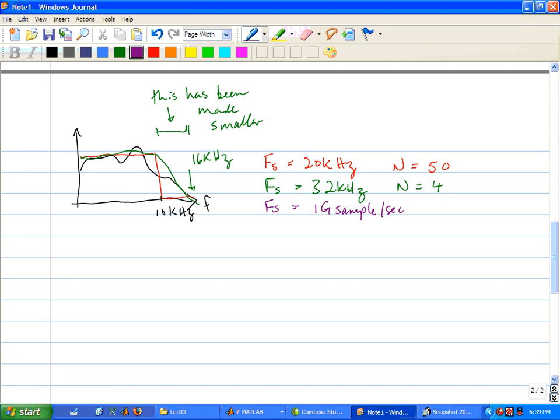Exactly. If I do the third option, the purple option, now I need a digital processor that's much more powerful, power hungry, and physically larger. I've really increased the burden on the digital processor. So here I have a relatively simple digital processor, whereas here I'm requiring a very complex DSP. So that's essentially the trade-off.